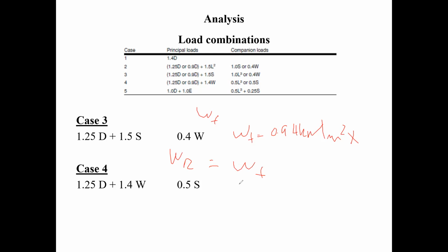Is it going to be the spacing between the... Exactly. It's going to be the spacing of the studs, 0.6. And then, of course, what is the load factor for case number 3? 0.4. This is your load factor. That's for case number 3.